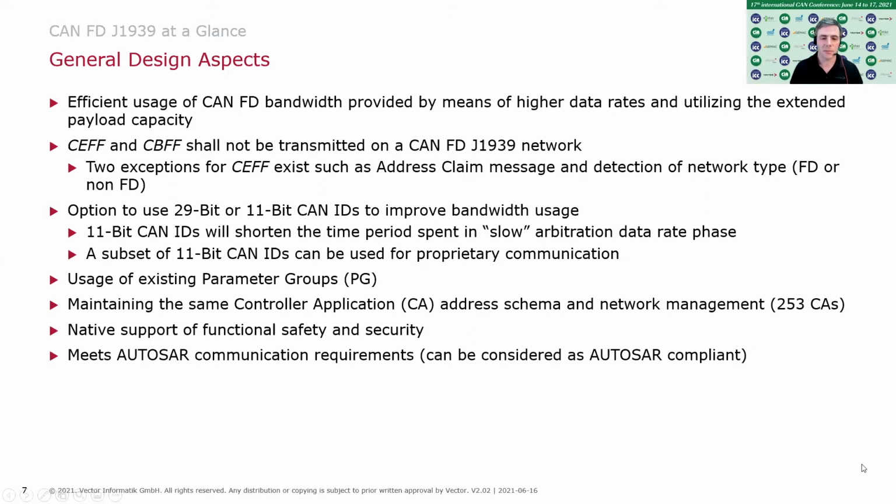For very specific functionality, such as address claim, which is mainly active at startup, and the detection of the network type: if you utilize the new FD protocol and attach this device to a legacy J1939 network, then for this purpose it is allowed to use the classic extended frame format for figuring out to which data link it is connected.